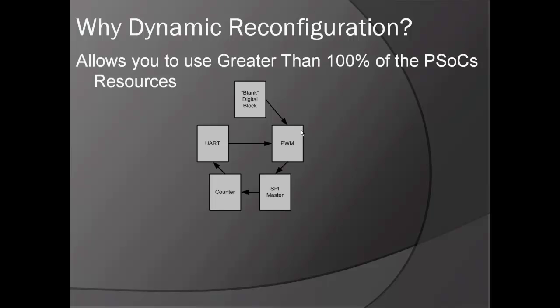Or say you need to read data from an SPI slave. Again, you probably don't need to read the data all the time, so the time that the data is not being read, the block can be reconfigured to accomplish another task other than an SPI master. Another task could be having it configured as a counter to count specific events. Again, this counter may not be needed all the time, so the block can be reconfigured for another function, such as a UART transmitter to transmit the results of a count to another device or PC.